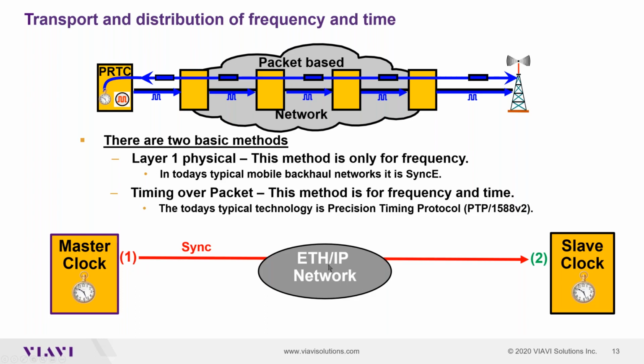The sync message goes over the network and is received by the slave. The slave looks at its system time when the first bit of the sync message is received and says, yes, I received it at this time. This is now time 2. Okay, it has now more or less a downstream delay, but it needs to know the round trip time, because the sync message timestamp is when the message leaves the master. But the slave needs to know the delay through the network, because this is a correction value. The network delay has to be added to the timestamp received in the sync message.